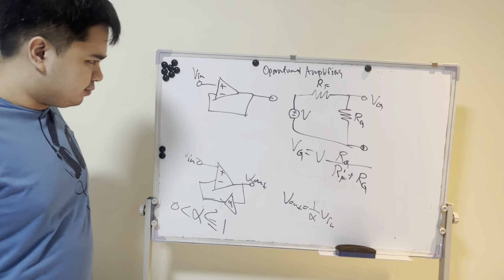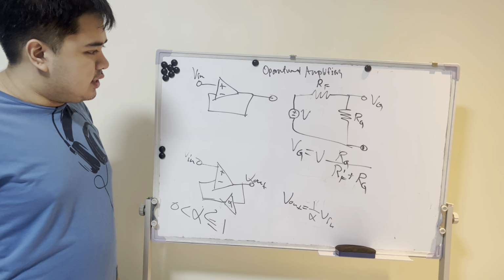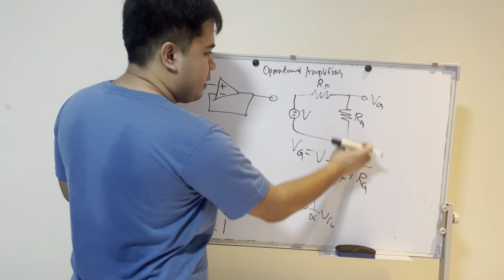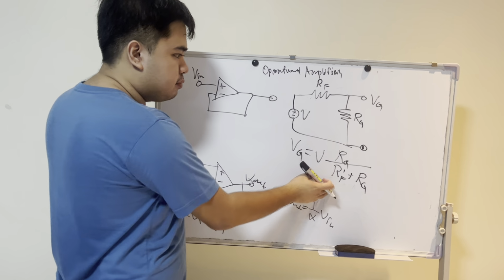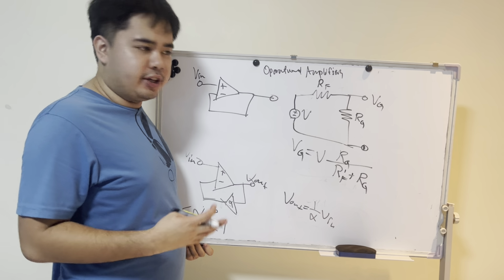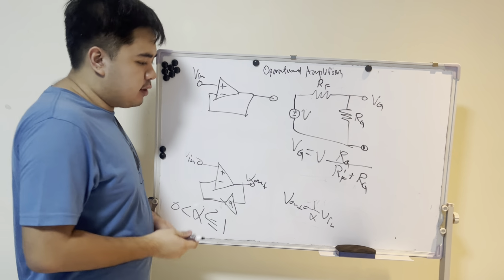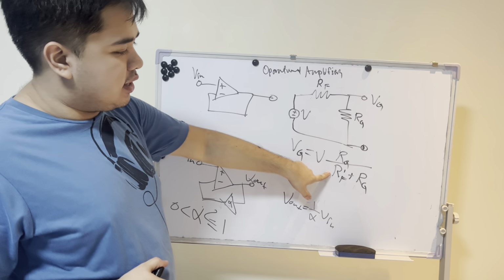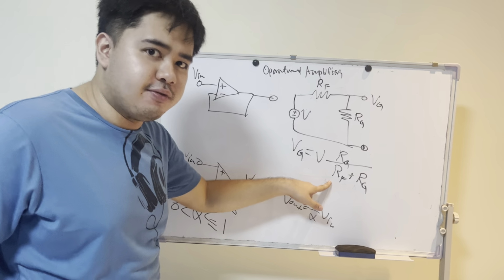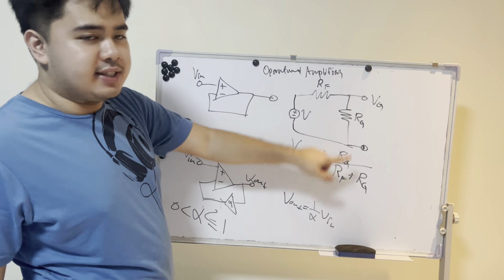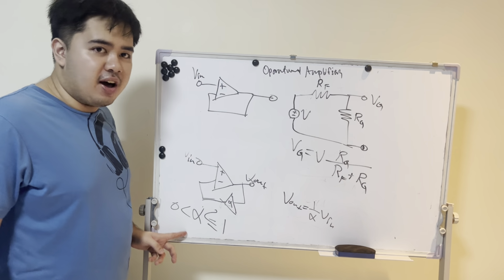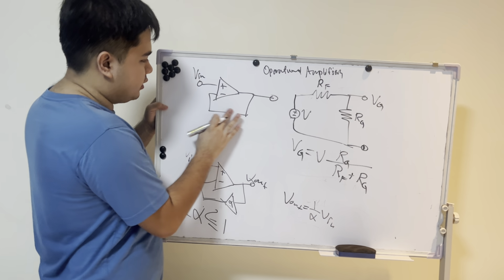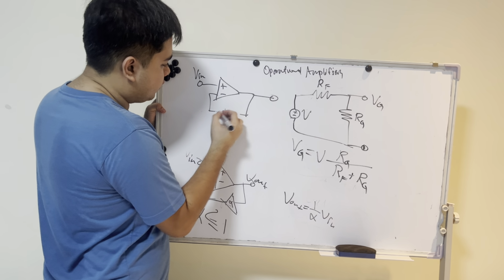And that is the voltage. As we can see here, this is just a constant depending on the resistances. It could be a sort of attenuation or gain. If we look at here, RG is on both the numerator and the denominator, and since RF is a positive value, this means that this is less than 1, which is befitting of alpha here. So we can use that in order to attenuate the voltage here. Right?